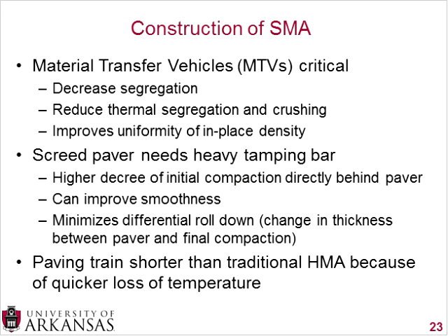Now over on to the construction side. It's highly, highly recommended to use a material transfer vehicle or an MTV. Now these are often found on asphalt concrete job sites. What they are is they're basically a small little pug mill. They can have heating units if you want to get the temperature back up. But what it allows you to do is take mix that's maybe been sitting in a truck for a little while.